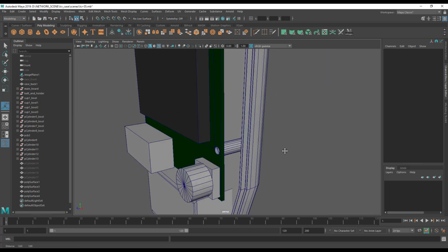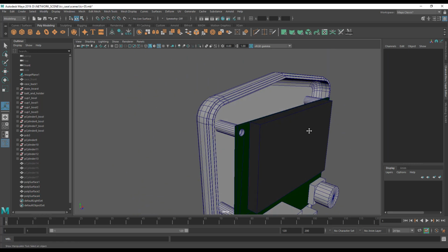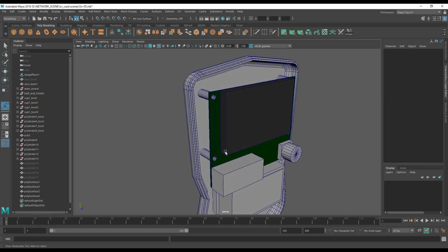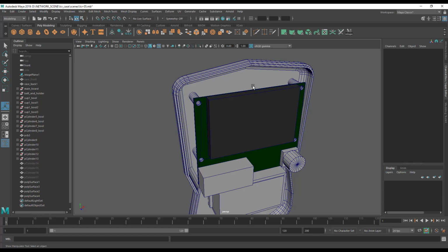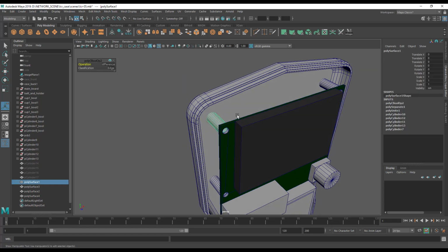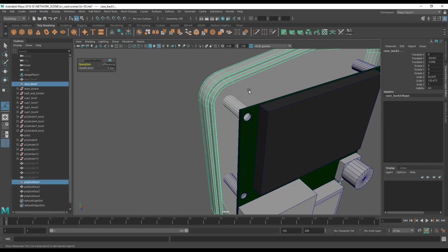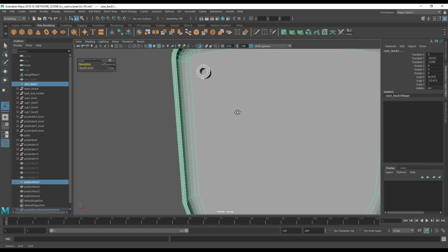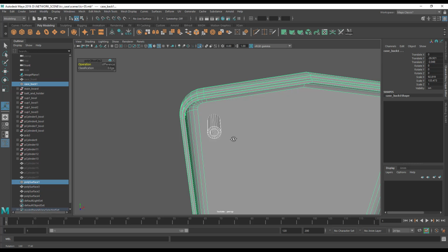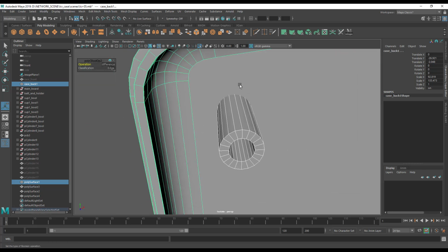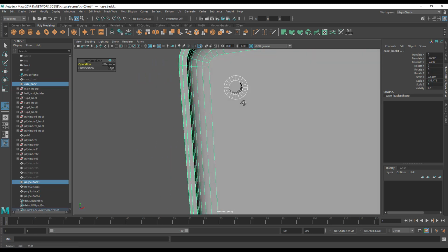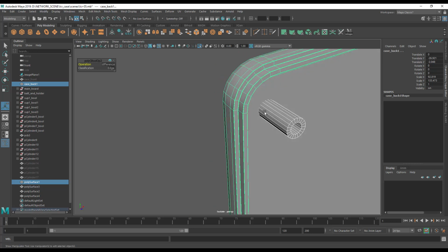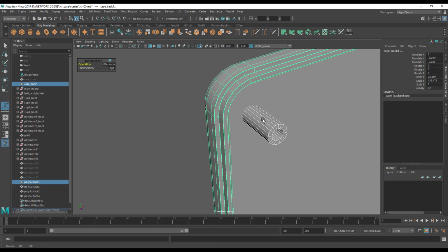Okay, so we are done. That would act as a support pillar. Now 4 screws can go through here, and you are almost done. However, because we're 3D printing, and me personally, my 3D printer is not like the best in the universe, I like to have some extra support. So what I like to do is provide some little support pillars around the base of this to help stabilize it as it's printing. It also helps to create a stronger bond with the case.